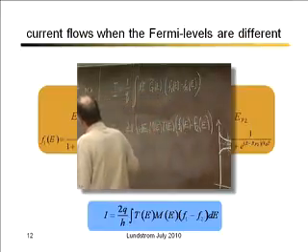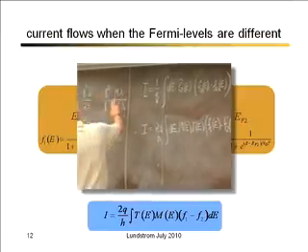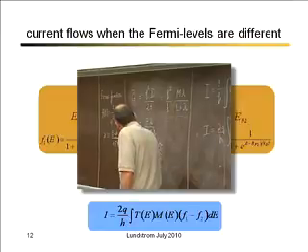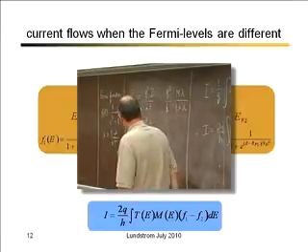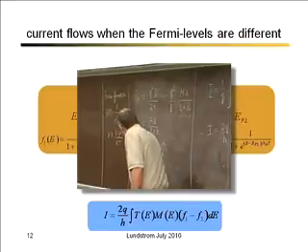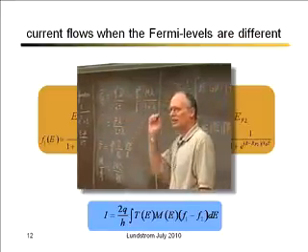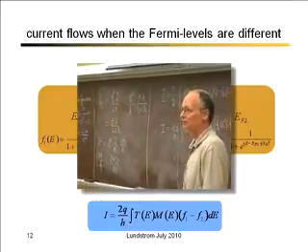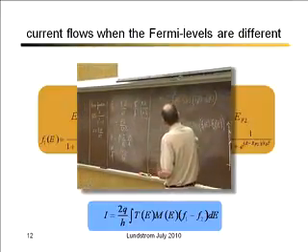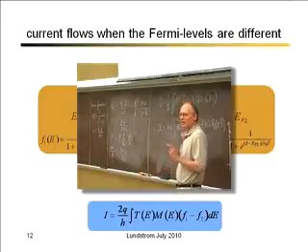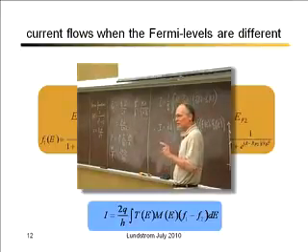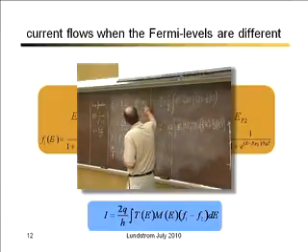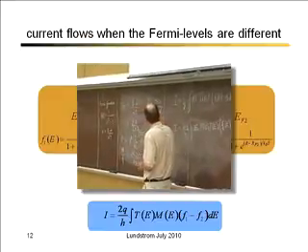And if you relate this to what Professor Dada discussed, when he lumped some of these constants together, M was the density of states times the average velocity in the direction of transport, and there's a constant h that's involved in there. I'll discuss that very briefly, and I understand Professor Dada is going to say more about that in the afternoon. But M is a dimensionless number which tells us how many channels are there at an energy E to conduct current. Now T is just a way of writing mean free path divided by mean free path plus L.